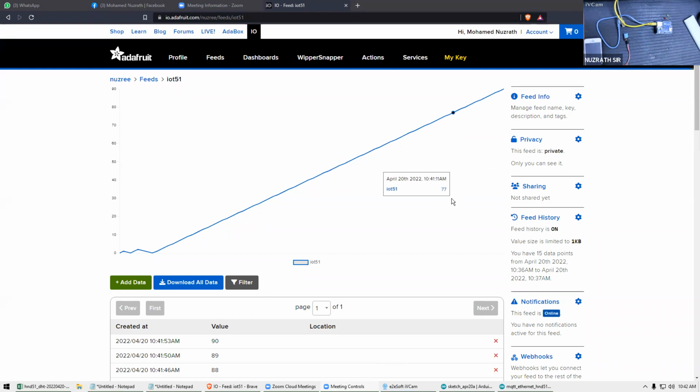Now what we shall do next, I'm going to take this one and wire it up. I'm not using the breadboard, children. You also can note it down if you want. So next step, that is version 2 we are doing. Actually, step 1 we already did. So the ground pin I'm putting to the ground pin. Five volts, I will put to 5 volts here. And the signal pin, I'll put to pin number 7.